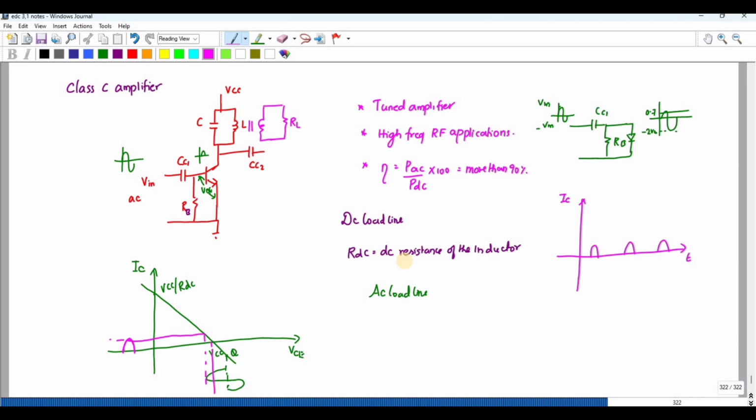So when a signal of many frequencies is present at the input of the tuned amplifier, it will select and strongly amplify the signal of the resonant frequency while rejecting all other frequencies. The pulse is a combination of different sine signals, so it has a different range of frequencies, but the tuned amplifier will select the particular frequency.